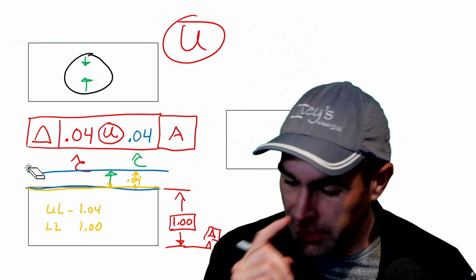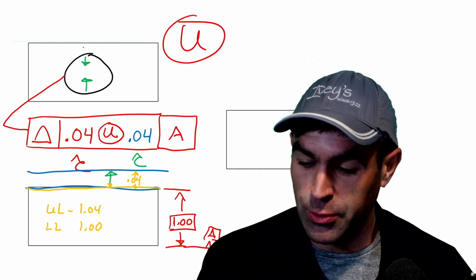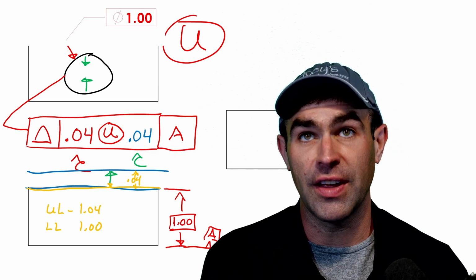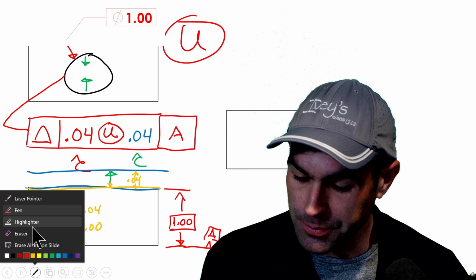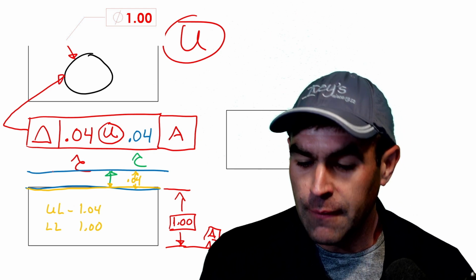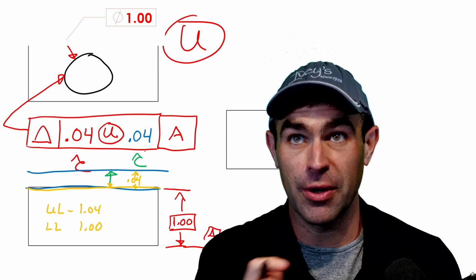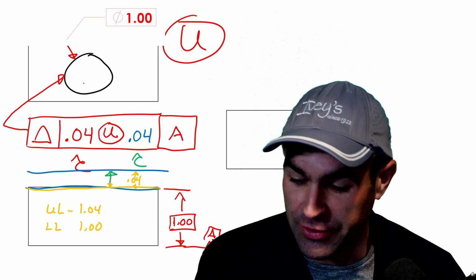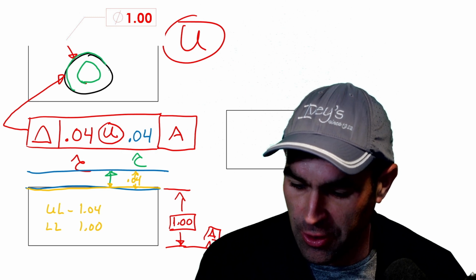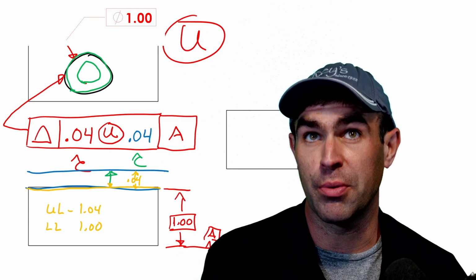Now, since I've got this set up like so, what if it applied to this hole? I know you don't see holes with basic dimensions all the time, but it is possible. We can do it. So in this case, I'll put an arrow on this leader and read this out again: profile 40 thousandths unequally disposed, 40 thousandths in the direction that would add material. So toward the maximum material condition, which in this case is in here. So our tolerance zone only makes the hole smaller relative to that original true profile.